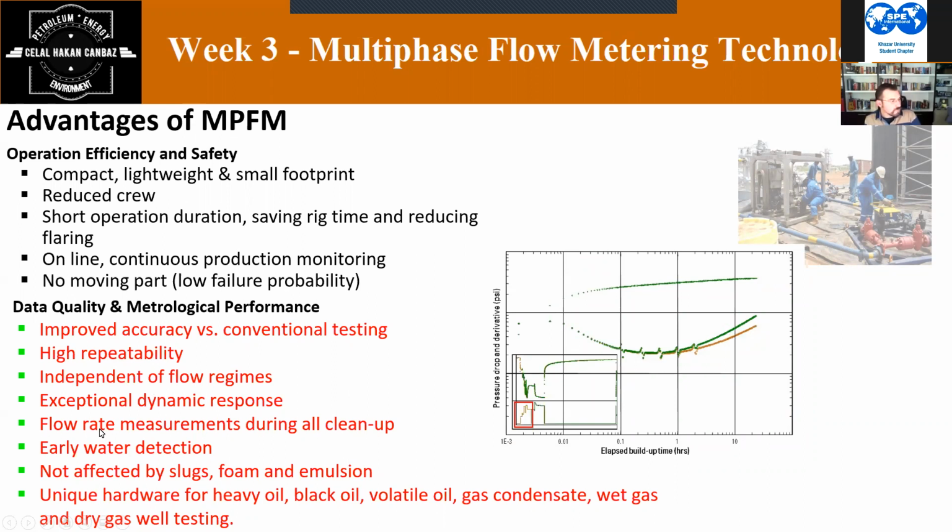Okay. Early water detection compared with the separator. So that's why they are using that for water coning issues. Not affected by slugs, foam, or emulsions. This is for the measurement of surface water testing. It's a very challenging issue, actually, foaming and emulsions.